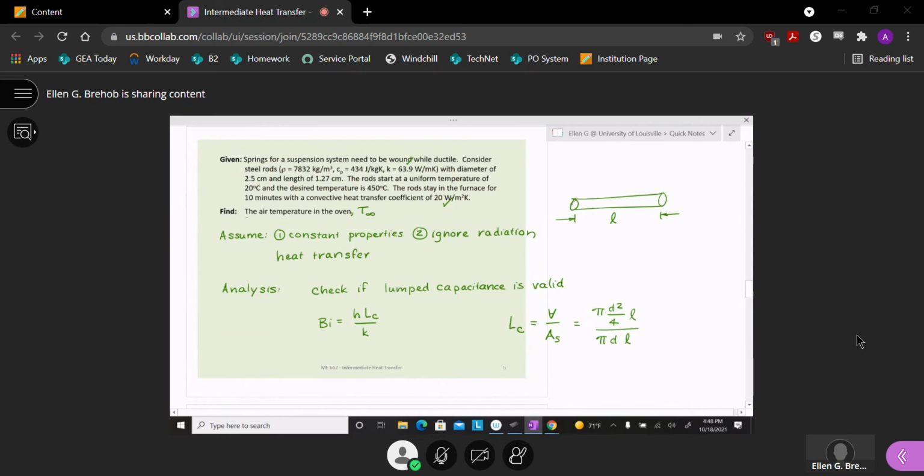All right. And let's make a note. Okay. I am leaving off these little surface areas for this length. You know, and I didn't calculate it. We could put it in and see how much difference it makes, but it's a pretty small difference to consider. So let's add another assumption. I'm ignoring any heat loss from the ends. Okay, so the only surface that I have convection removing heat is the cylindrical surface.